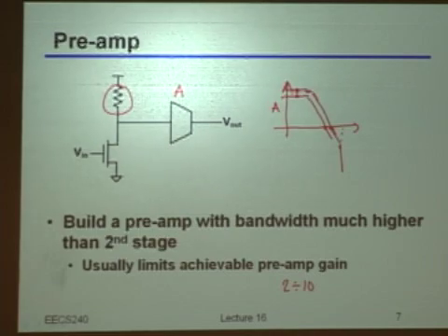That's normally the typical preamplifier configuration used. And so I can indeed get a boost of gain even smaller than 10, right? 2 to 4 or something. So it's good if you need just this small boost, right? But you cannot really use this technique everywhere, because the advantages that you get are not so many.